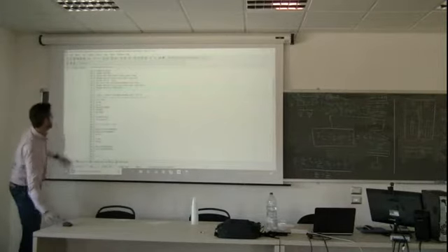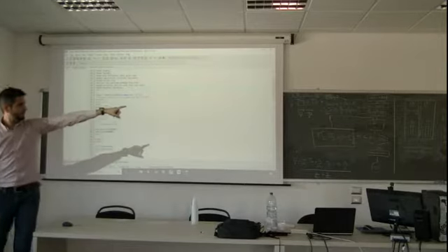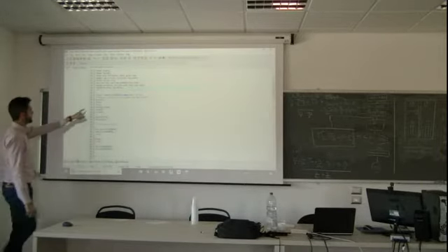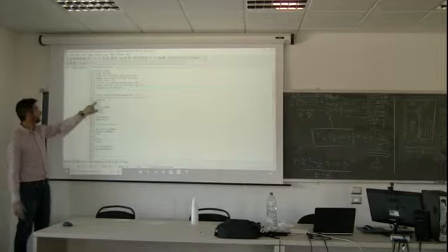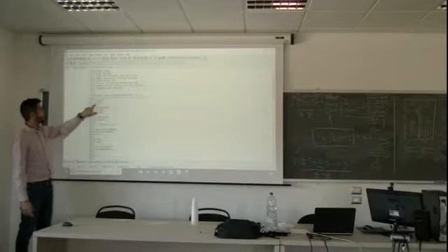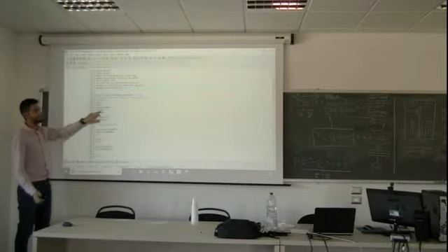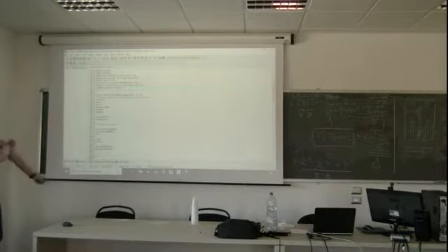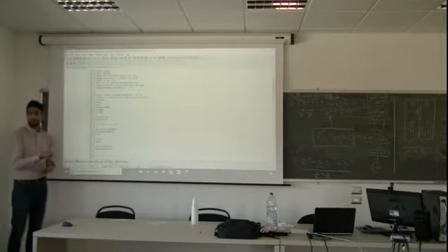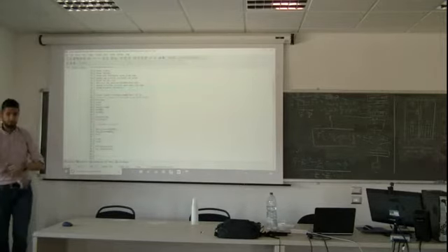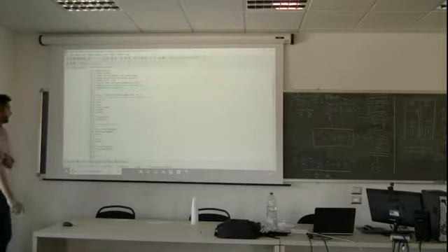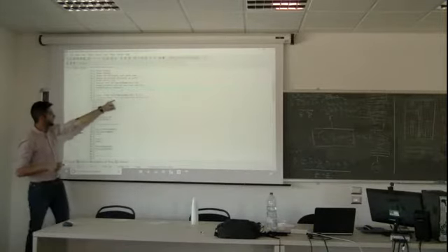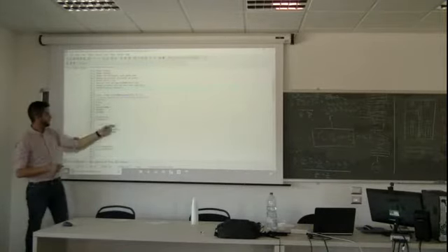Okay. Now, first thing we have to do: input parameters. We define T air is 25, T wall 10. Thermal conductivity, 5. Density, 1000. CP, 800, whatever, we don't use it now. Heat generation, 500. Thickness, 0.05, 0.1. That's direct, right? This is the physical properties and geometrical data input. Let's go to the parameters input.